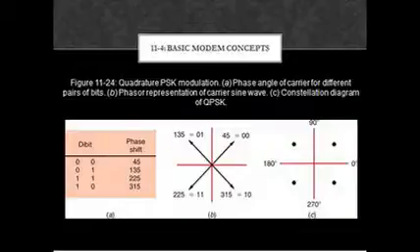For example, it is common to use phase shifts of 45 degrees, 135 degrees, 225 degrees, and 315 degrees as shown in Figure 11.24b. The diagram in Figure 11.24b is called the constellation diagram. It shows the modulation signal in the form of phasors. The length of the arrow or phasor indicates the peak level voltage of the signal, while its angle to the axis is the phase shift.